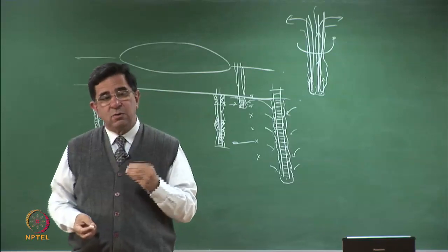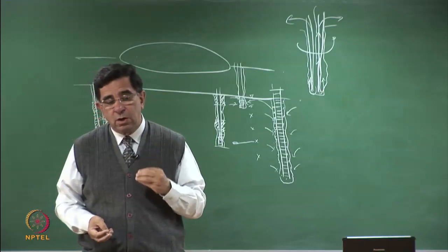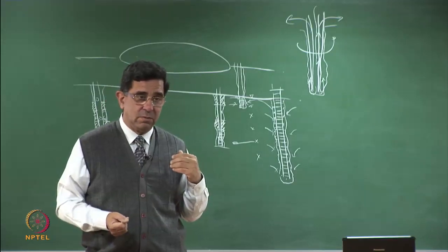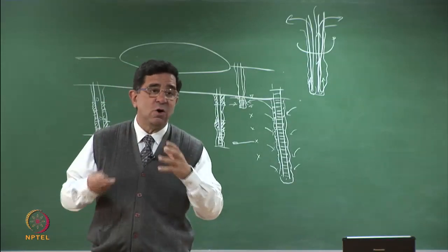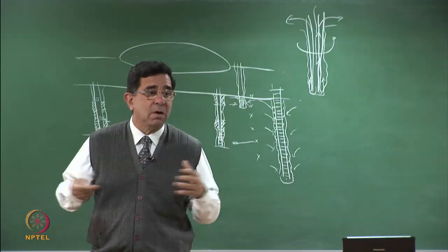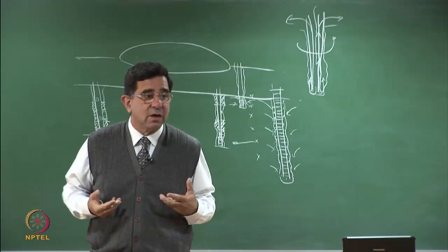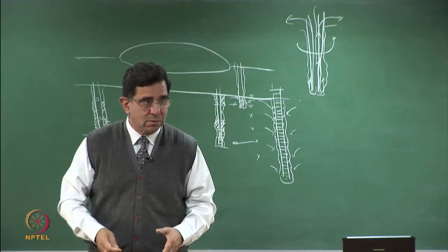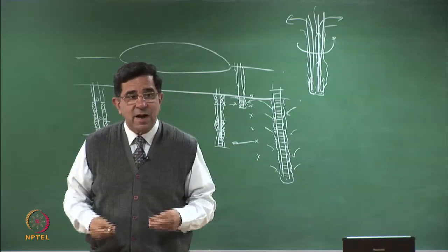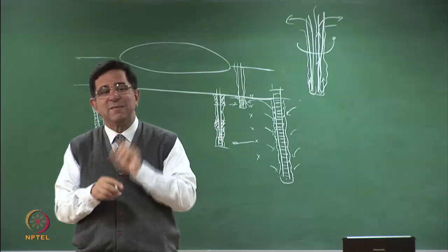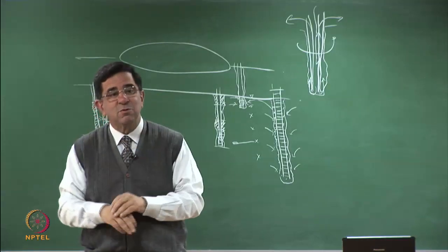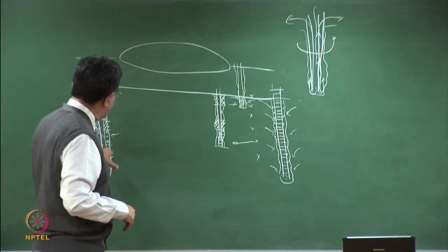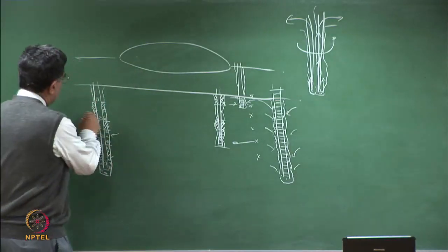So basically, we seal the hole, especially for applications like ours. You see, please understand, in a normal well, you are not trying to stop water from coming in from every level. You want water for drinking purposes or irrigation purposes. You want all the water to fall. Is that right? Here we are trying to say we want water from a specific place. Therefore, this sealing becomes so much more important. So a multi-port device has multiple seals and water comes from there.